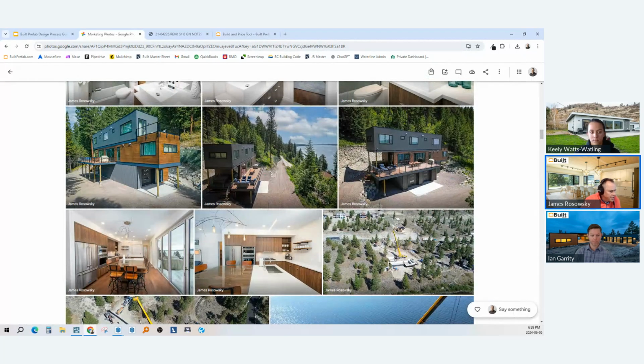Do you lose interior space by going to the high building envelope? Not a lot. The wall goes from around 7.5 inches thick to maybe 8.5, 9 inches. So over the course of 14 feet, you lose a bit. The only reason I mention it is that it doesn't sound like much, but if you're designing millwork or something that needs to fit in there, even windows and doors, those inches count. And so that's why we need to know what you're going to do.